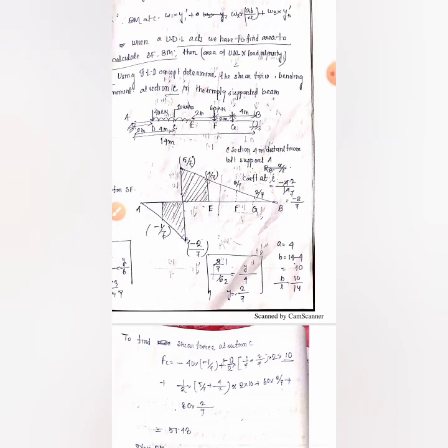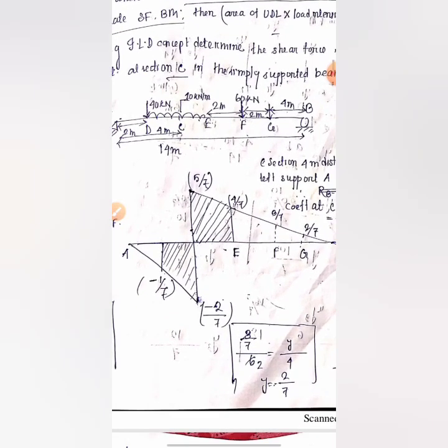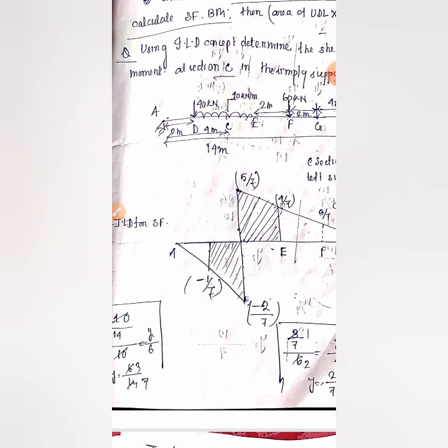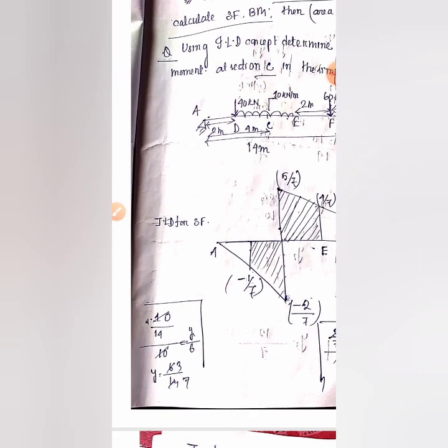First, what I have done is I have made the projection of all the points at which the loads are acting. I have seen in the question that a 40 kilonewton load is acting at point D. I have drawn it, and with the help of these values I have found the ordinate y1 with the help of similar triangle property, and the value of y1 is minus 1 by 7.